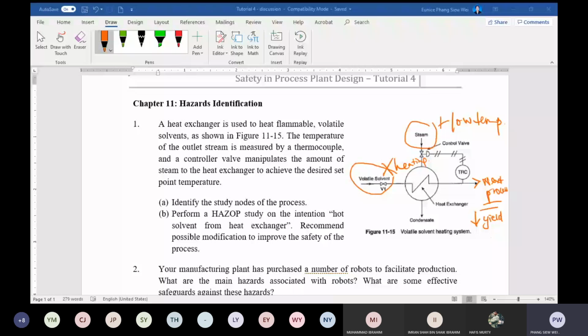When we do HAZOPs, we may realize something like that, and say, hey, we actually don't need 100, we only need about 70. That's where you can put in and say, let's take a look at this. We are going to reduce the incoming temperature from 100 degrees steam to 70 degrees, because 70 degrees is safer than 100 degrees. That's what we call process improvement.